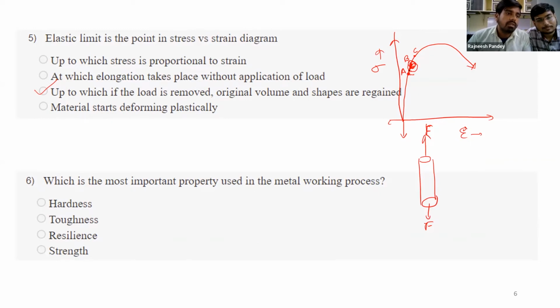But the first plastic deformation should start from the yield point. At the yield point, we generally consider 0.2% strain. This is the standard that has been made in order to handle a smooth curve like this. How are we going to define the yield point?